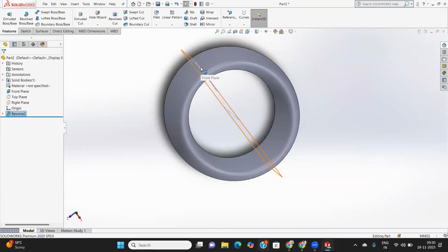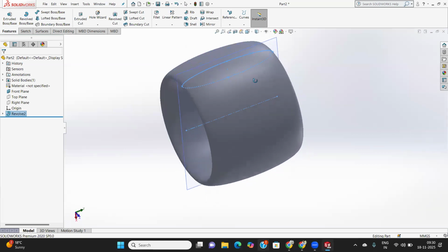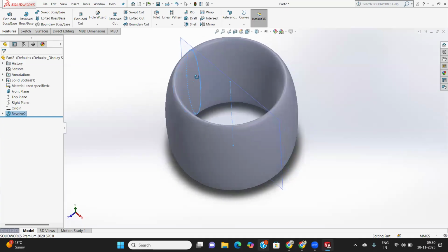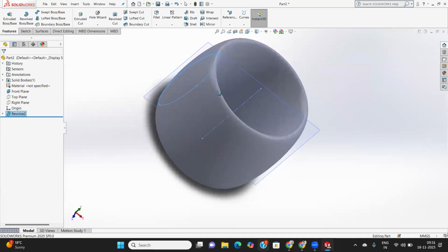This is a turbo casing, right? This way you can create it like that. And if we make a Revolve Boss Base, we need to make a center line on that, because we have the axis line. Without the axis line, I can't do anything.